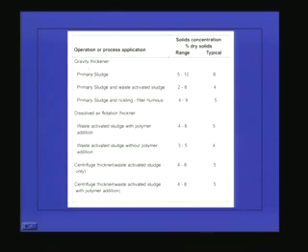And here I have again given the gravity thickener, flotation thickener and centrifuge thickener. The solid concentration varies from 5 to 10 and 4 to 8. So we can see that in any case, the solid concentration is most of the time less than 5%, and the remaining 95% is water.